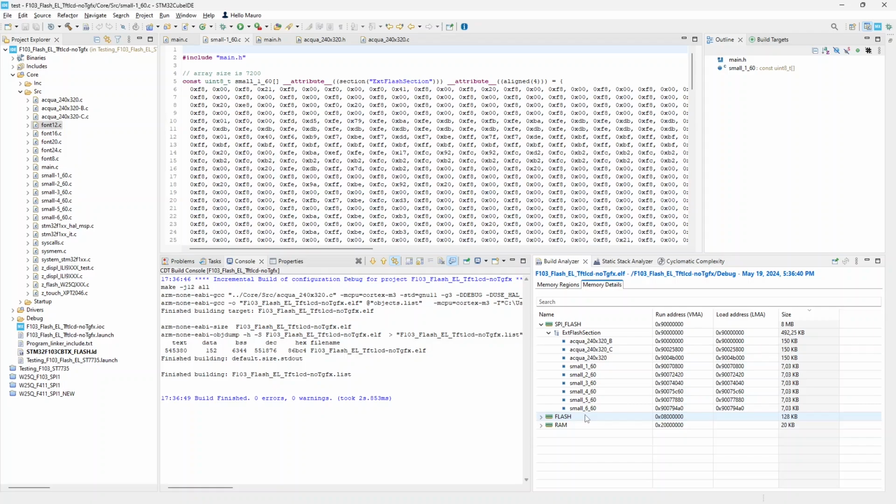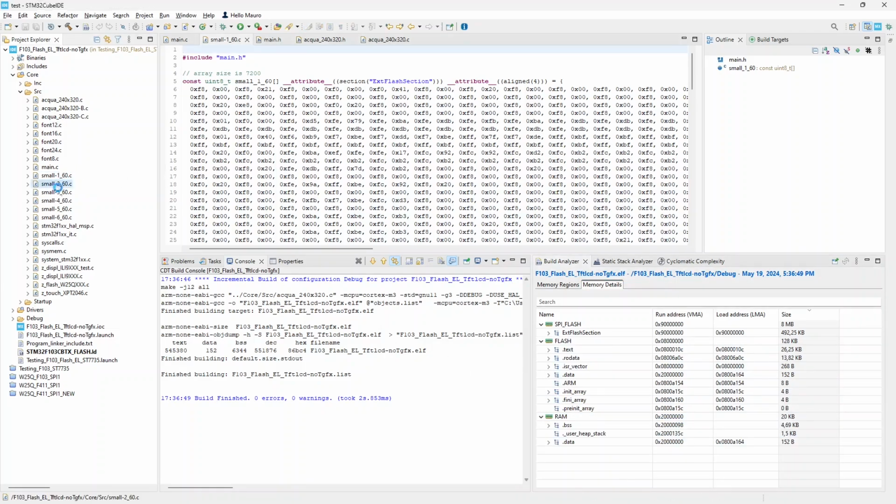So, we can clearly see the advantages we have using an external loader. I don't have to worry about the SPI Flash organization, where to store a picture, and where to start the next free area to store the next array. Linker does that for me. I just indicated the constants I have to store on the external flash, and the linker allocated the arrays on it. I can also easily change the configuration, moving pictures from the external flash to the internal one, and vice versa.